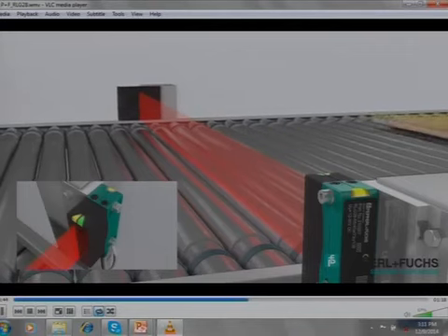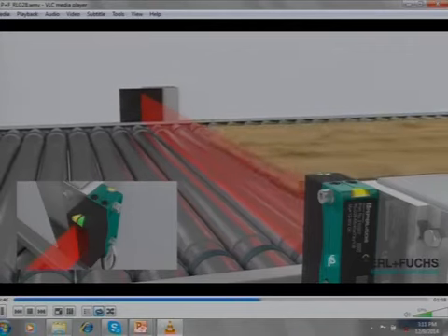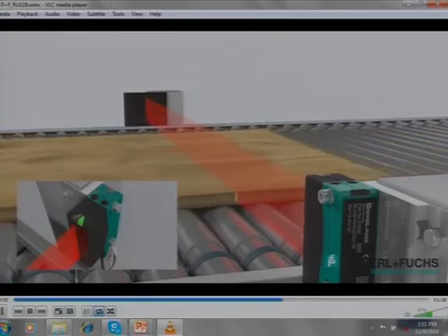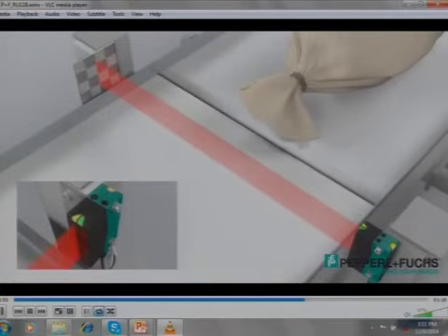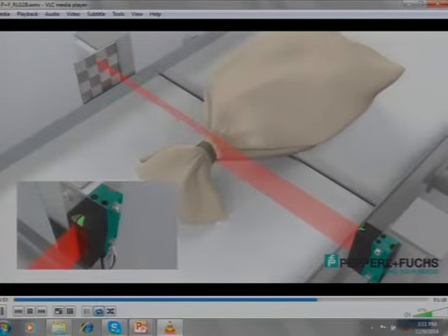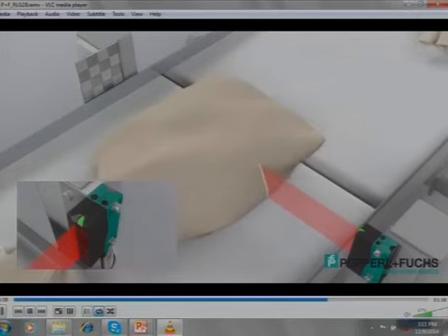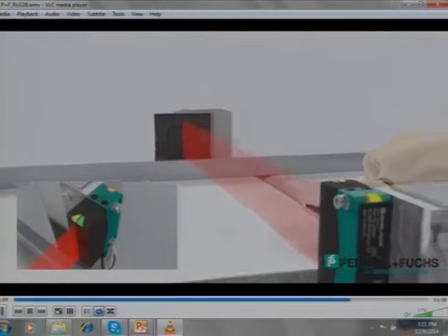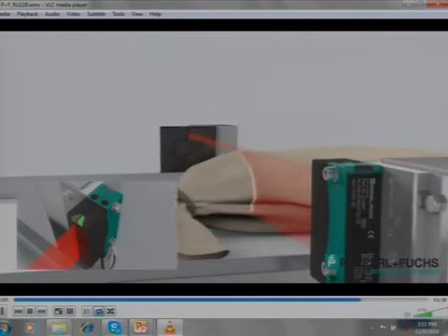So, it can be anything. It can be a vibrating component. It can be any type of component. We have done one application for an industry where they were supposed to detect a spring, right. A spring cannot be detected using a normal through beam or a retroreflective sensor. For that you need a wide band sensor, and this was a sensor that was able to detect the spring.